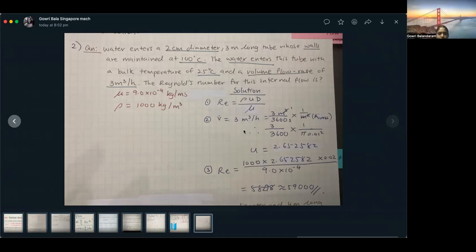I just didn't get the volume flow rate portion of it. Why we had to. Okay, see, volume flow rate, basically, if you remember, we had discussed the mass flow rate formula. The mass flow rate is basically density into volume flow rate. Many times, instead of giving you the velocity, they prefer giving you the mass flow rate. So using the volume flow rate, you can find the velocity. What is volume flow rate? Volume flow rate is area of cross section into velocity.